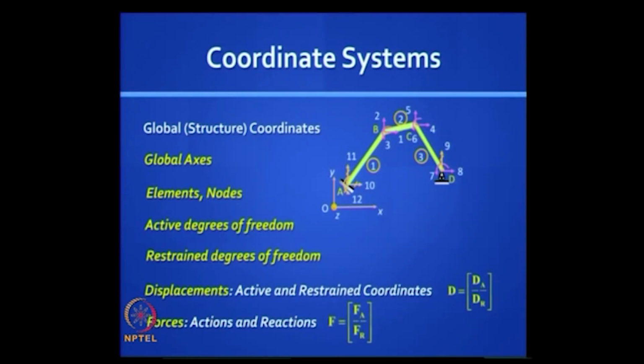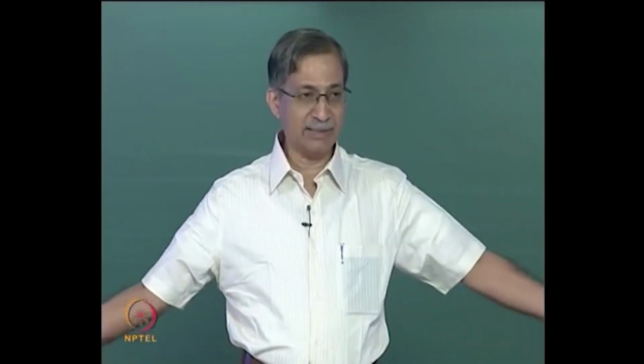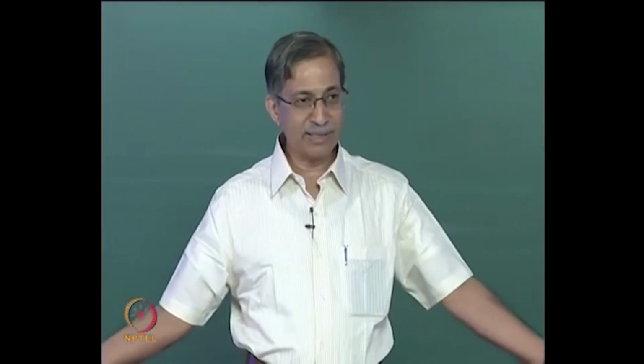At the joints, do we have to specify whether both can rotate freely, or both have to rotate by the same theta? If you do not say anything, we assume you are dealing with a rigid joint. For example, members 1 and 2 are rigidly connected at B if you do not make any statement. If you are dealing with the ends, the boundaries, there you have to define the supports.